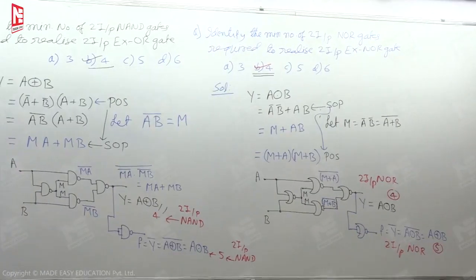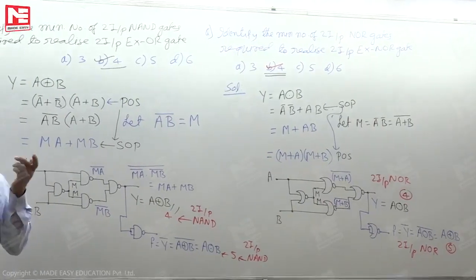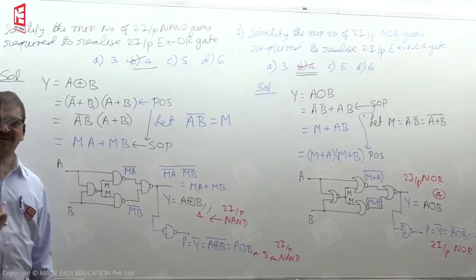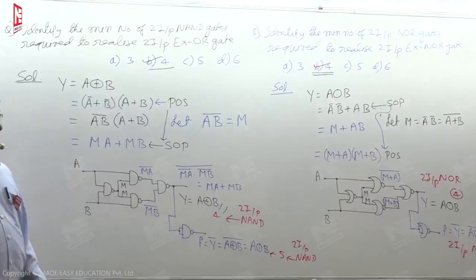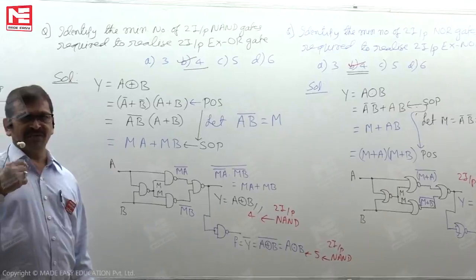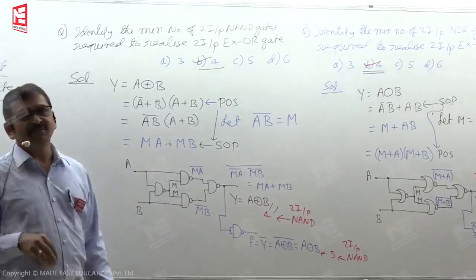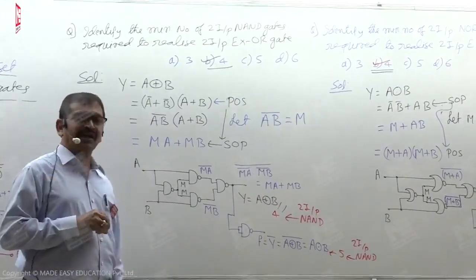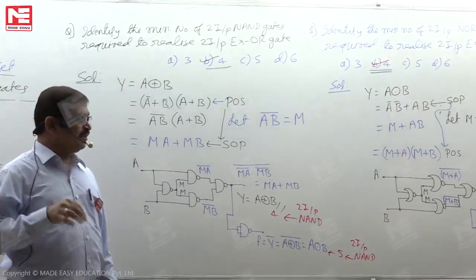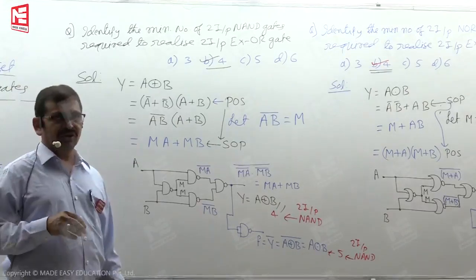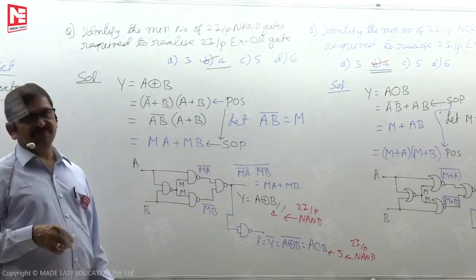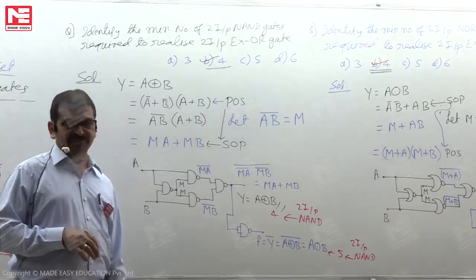Based on this, as we said, NAND gates and NOR gates are functionally complete or universal logic gates. We have the possibility to implement any digital circuit in general, or any Boolean function, or any digital system, just by using only NAND gates or just by using only NOR gates. That is the reason we call NAND gates and NOR gates universal logic gates, and the corresponding operators we name functionally complete set operators.